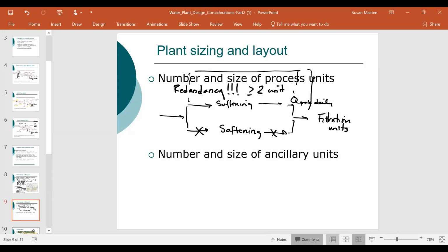So basically, these are deep wells, they're not affected by surface water, then yes, you not only don't need treatment, you don't necessarily need disinfection, and you don't need to monitor for disinfection residuals in the distribution system. If it is a groundwater under the influence of surface water, you do.